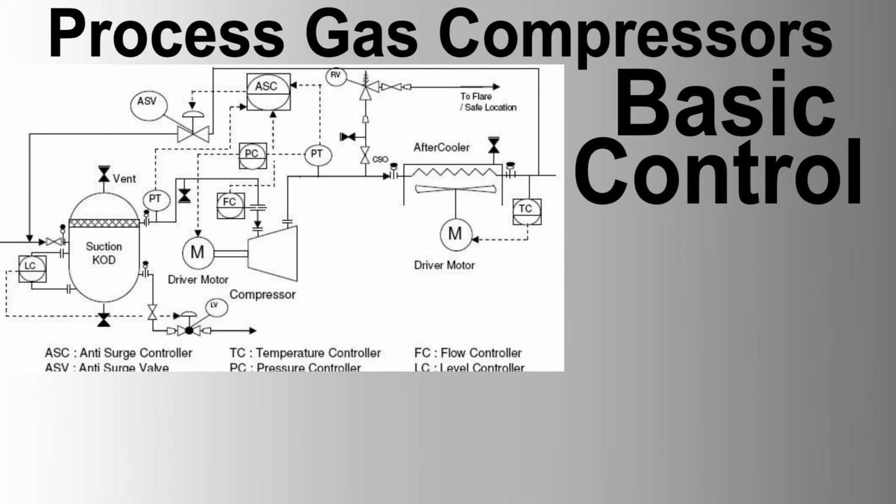B. Data collection and analysis. Vibration data acquisition: sensors send data to a vibration monitoring system or directly to the DCS. Analysis: real-time analysis of vibration data to detect anomalies or trends indicating potential issues. Alarm levels: predefined vibration levels that trigger alarms and potentially shut down the compressor to prevent damage.